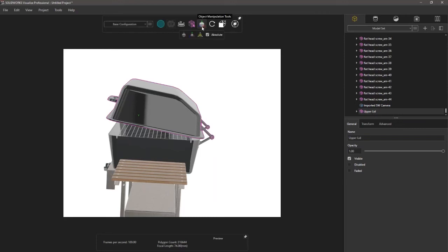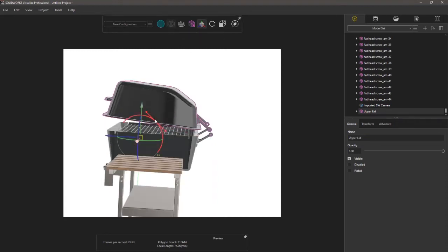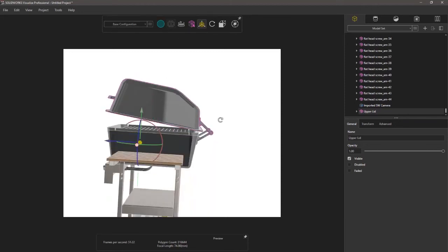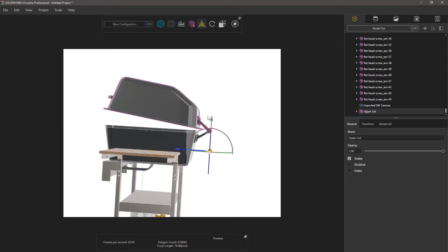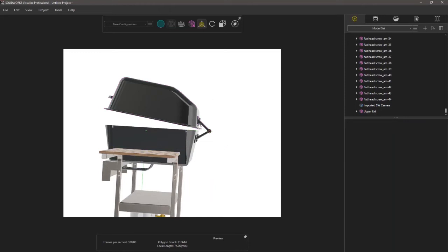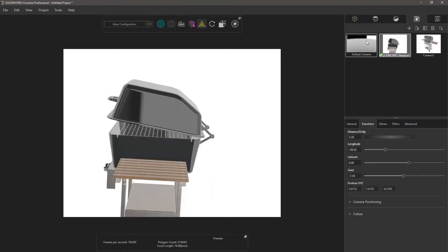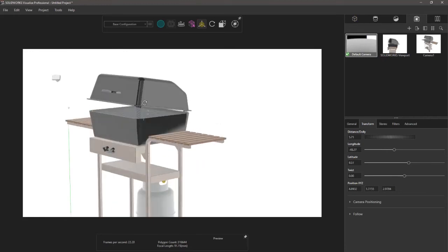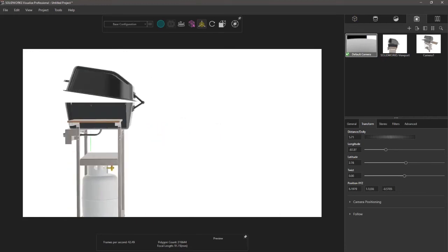and this is our transform tool. If I go to translate, by default it's going to have the wrong rotation pivot, so if I try to rotate, it's not going to do what I want. But the nice thing is I can move that pivot, and I only need to move it once for that group. Now, when I select that group again, once I adjust this pivot, it'll rotate about the correct axis. What I tend to like to do is, since I'm in a high perspective view right now, move to a no perspective or very low perspective view to manipulate that pivot. It just makes my life a little easier.